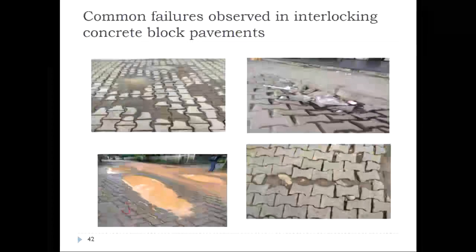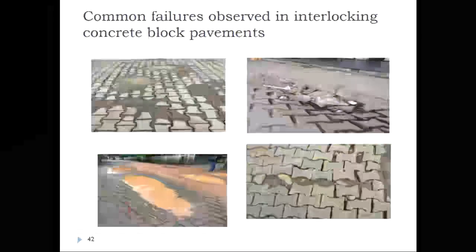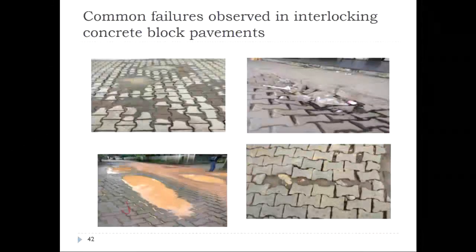The main advantage in the case of an interlocking block pavement is that you could remove these blocks and then do a recompaction. However, whenever you are planning an interlocking block pavement, or any pavement structure as a whole, you should provide sufficient subsurface drainage as well as cross surface drainage facilities. This is the success of any pavement.